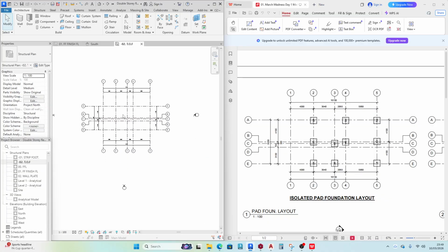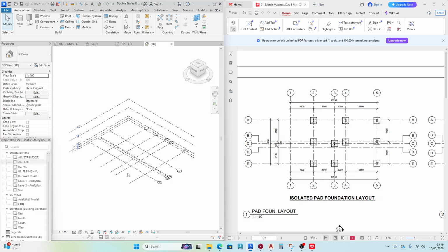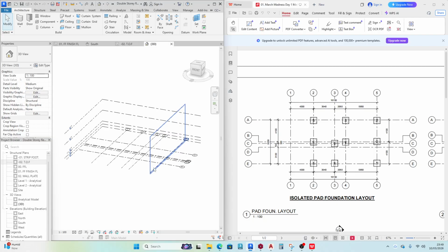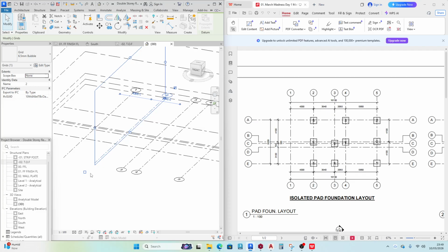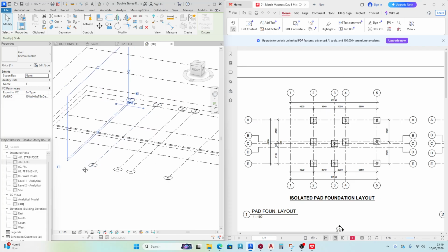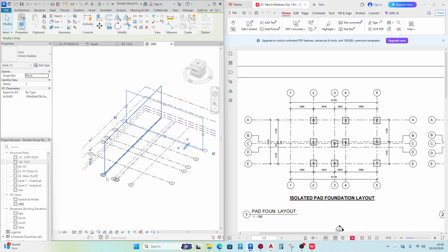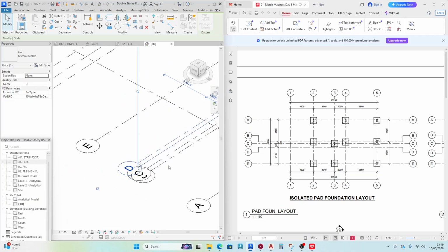So here we've set up the grid system. When I click on the house for 3D, you can see that we do not have any elements or any structures at the moment. When you select that, you can add the bubbles so that you can see the grid lines in 3D view also. If you wanted to, can you apply an elbow here?